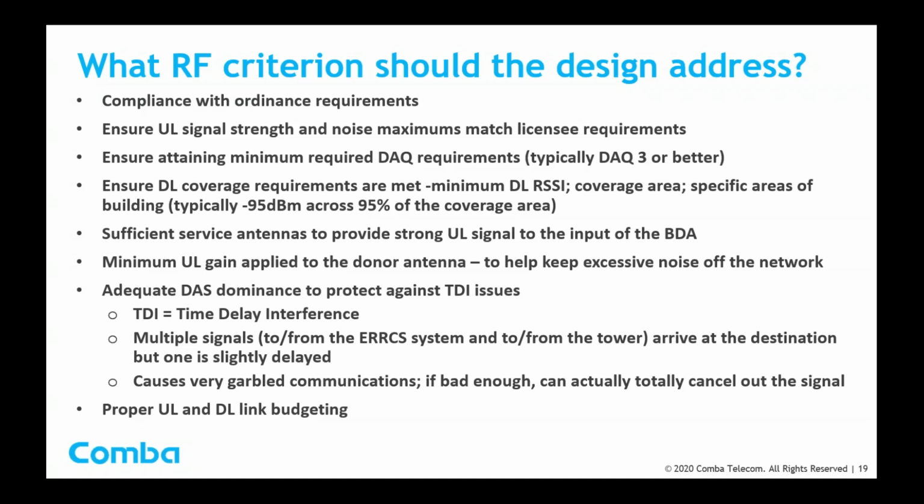What is TDI? TDI is an acronym for time delay interference. TDI is when you have multiple signals, either to or from the ERRCS system, to or from the tower, arriving at the destination, but one is slightly delayed. The delayed signal can affect the original signal to the point where it garbles the communications.